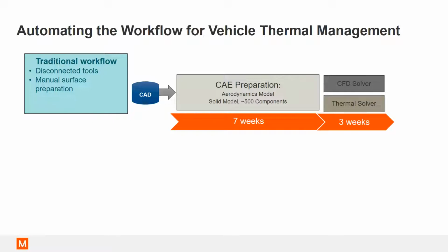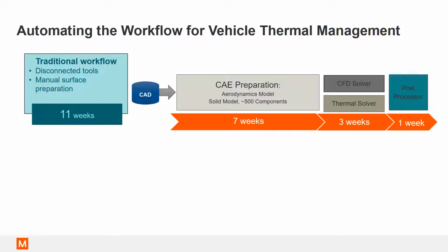With this kind of preparation, traditionally you would have a CFD model and another model for the thermal solver, hopefully both using the same surface if possible. Clients running long drive cycles need to send results from the CFD solver to the thermal solver. This data transfer is typically done only once or twice for a given simulation since it is time consuming. Once done, a different tool is used for post-processing as you require information from two different solvers, and this makes it difficult to analyze the results.